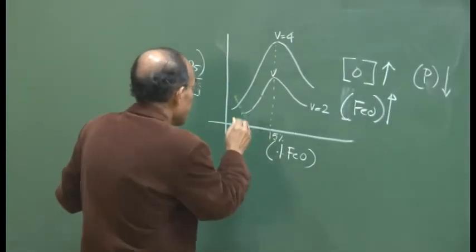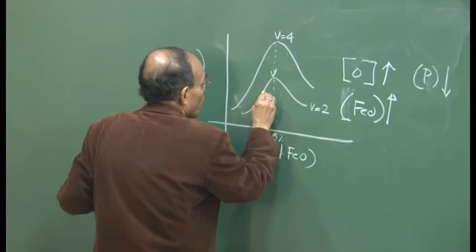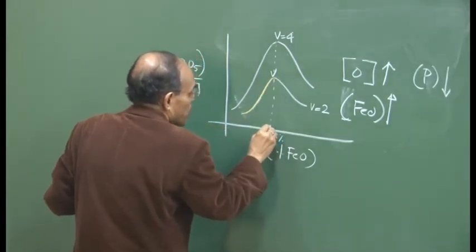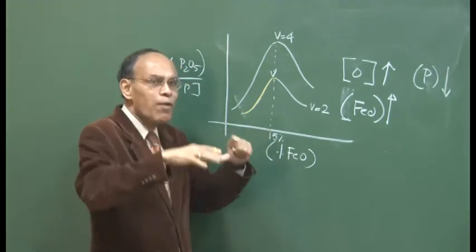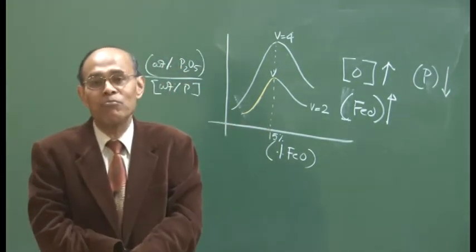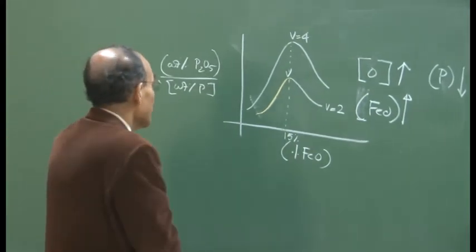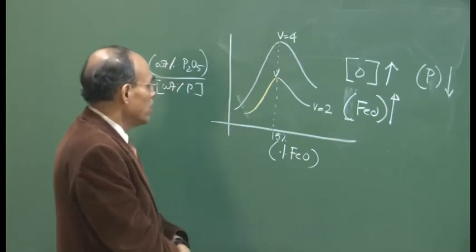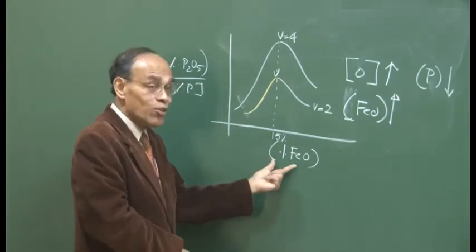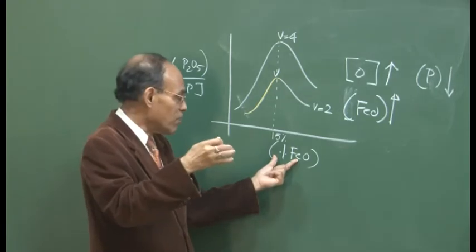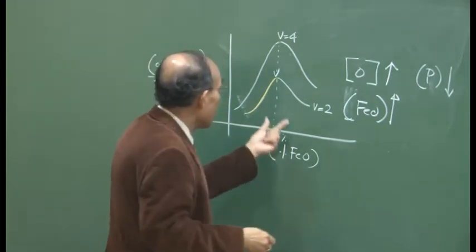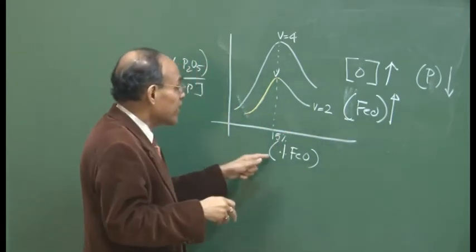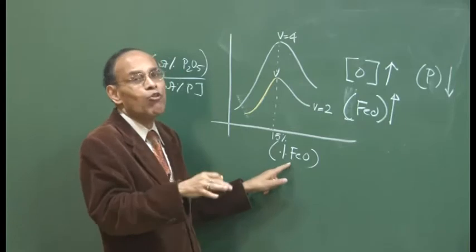So as a result, we can expect that as the FeO content increases, this weight percentage of 15% essentially tells us that we now have enough FeO in the system to impede the dissolution rate of lime. This also tells us that towards the end part, when the process is ending and the carbon content has come down and we are blowing, there is a chance of the slag FeO building up very rapidly.